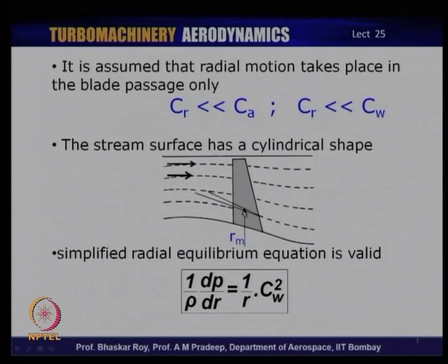So, if you take the meridional path of the flow, at any point on the meridional path the flow would automatically have an axial component. If it is passing through a rotor blade or it just passed through the rotor blade, it will have acquired a whirl component as shown here, and then because of the nature of this meridional path, it will acquire a certain amount of radial component. So, because of the geometry of the flow track, sometimes the flow acquires a radial component, and that is inevitable because of the aerothermodynamics of the flow as it is going through the axial flow turbine.